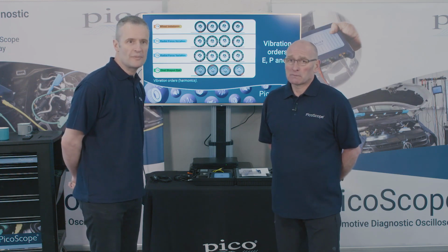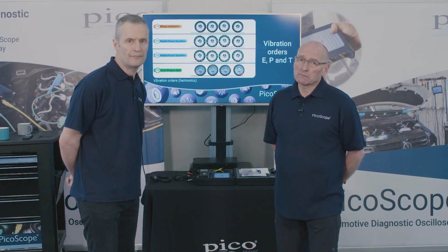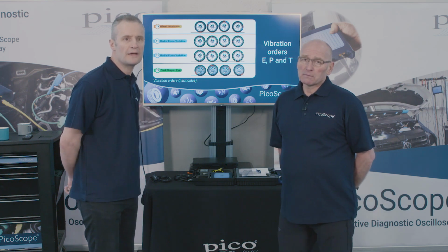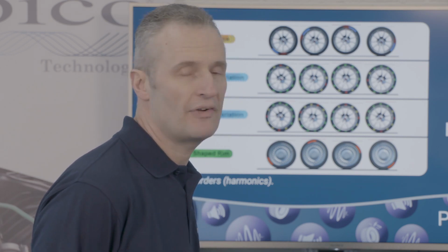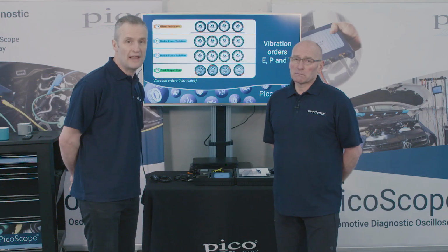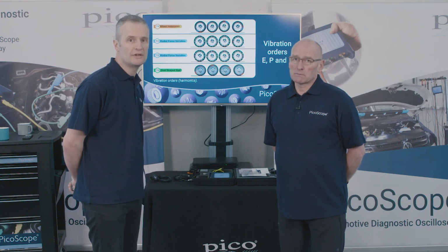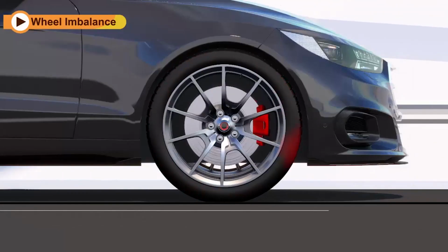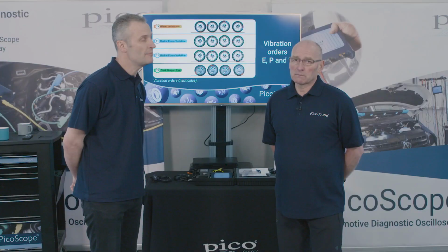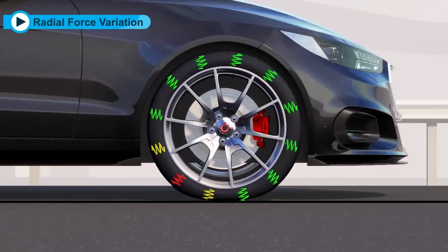Once the vehicle has come in for its first set of tyres, rim replacement, whatever it may be, running the radial force variation balancing on those rims will minimise the risk of any vibration, first order or second order, by, as you said, Frank, phase matching the tyre to the rim. There is an allowance within the rim for deformation, and there is, of course, a tolerance in the tyre, and if we can match those accordingly, we can again minimise the risk. That's what that's about.